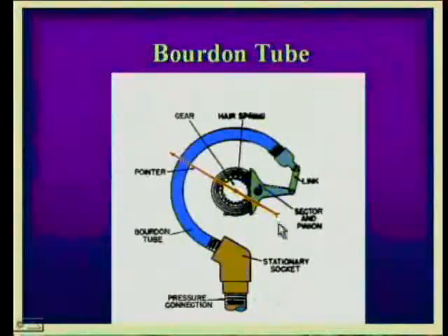You can see the Bourdon pressure gauge in color form. The tube we can see is in blue color, and the links are shown in green color, and the sector also, and the pinion in black color, and the pointer again. The one in brown color is connected to the pressure side, and the pointer is given in red color. So this is how we can measure the pressures.